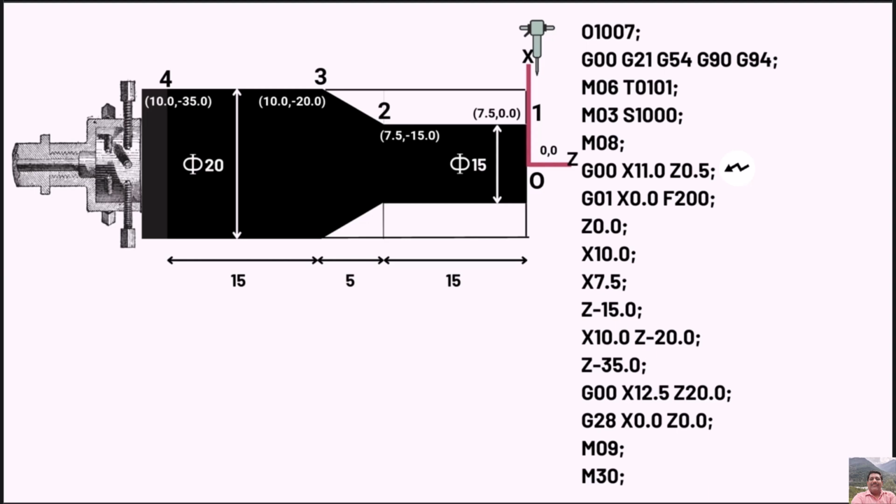Now machining operation will commence, so G01 command is invoked, since it's obviously a linear interpolation, and the tool is shifted to datum by using command X0.0. We need to provide feed rate as well, so we will use F200 for 200 mm per minute feed rate.